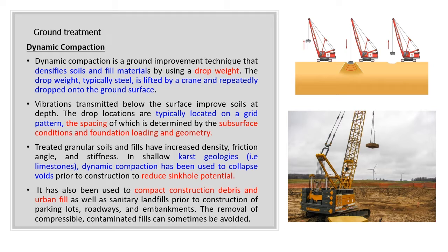To determine the allowable bearing capacity, accurate measurements are taken of the penetration achieved by application of a particular energy, known load from a known height. Analysis of the levels can be used to calculate the amount of void closure and the degree of densification. Using dynamic compaction, a bearing capacity of 50 to 150 kN per square meter can be achieved. Greater bearing capacities may be achievable, also depending on the ground condition.